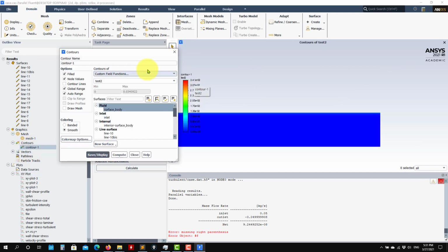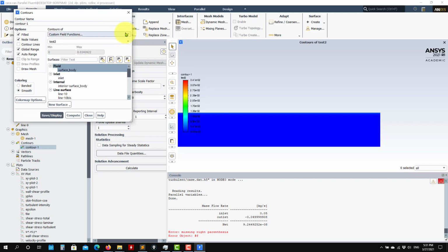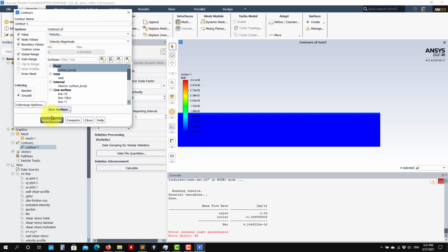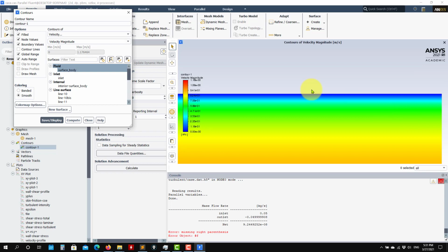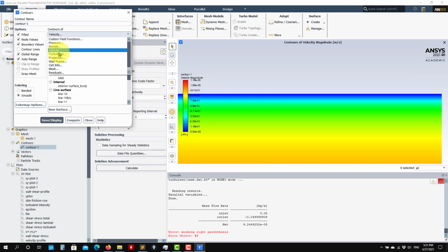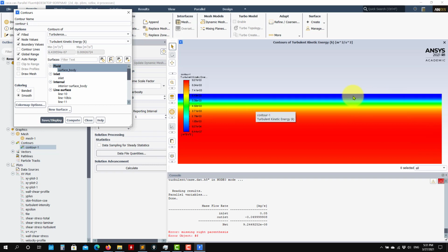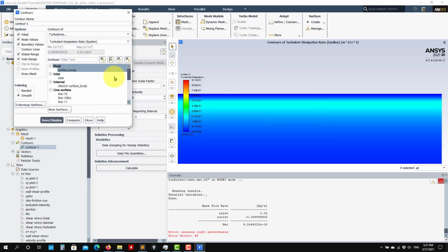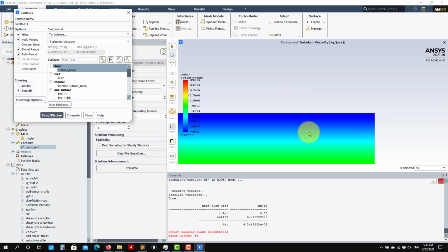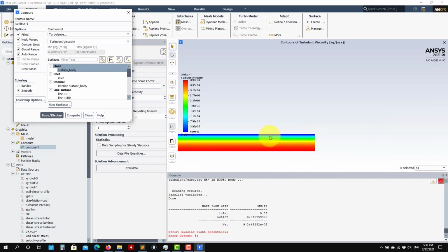Again, go back here and you can see your colors, everything. So just revisiting this one, that is a wall resolving mesh. Close to the wall, you have this one. And remember that you plot the turbulence quantity, turbulent kinetic energy. Close to the wall it is 0. This will be somewhere in the buffer layer, okay? And epsilon also, the walls start to dampen everything, okay? And then turbulent viscosity, you have it there, okay? You have your turbulent viscosity.